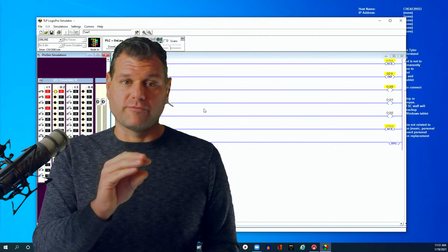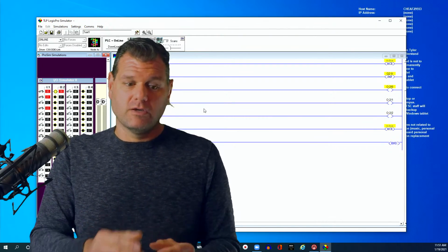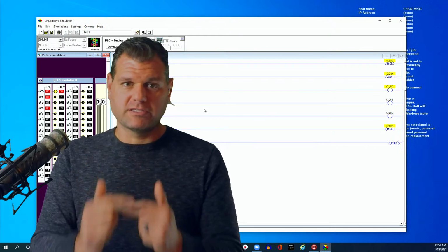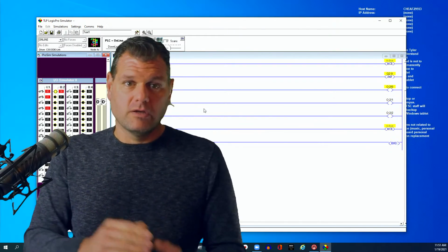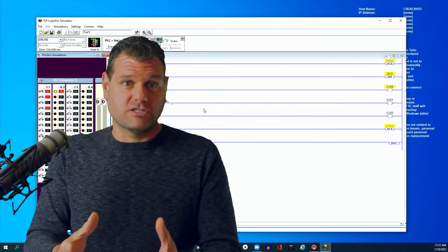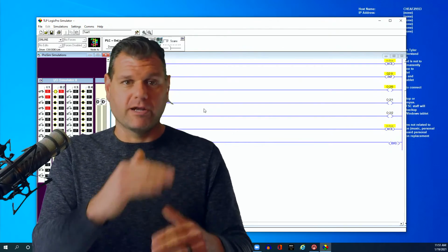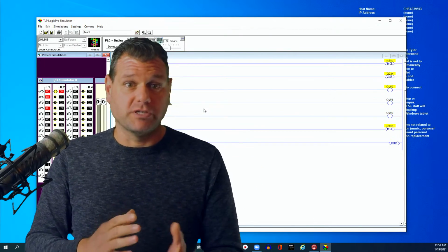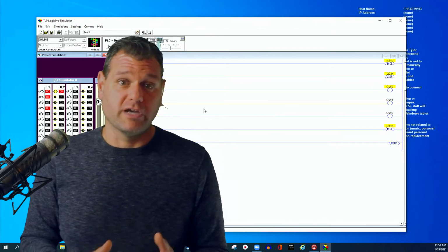And the cool part about nesting is that you can make individual programs that are only for certain things. So if you had a braking system that slowed something down when it was overspeed, you say go to subroutine. It does all the braking systems to get everything in order for braking. It slows something down, and then when the brake is achieved, it'll go back and say, okay, now you check air pressure, whatever it needs to do, and then it goes back to the original. So subroutines are just a way to cleanly break up your program into something that you just don't use all the time.